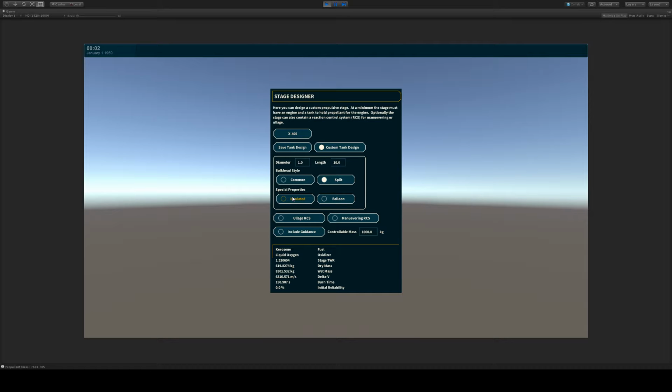You also have the ability to change this here, obviously. So we're going to go ahead and make this again something analogous to the Vanguard first stage, which is a 1.14 meter diameter. And you'll see as we do that and press enter, this is now updating. And so again, 12.2 meters high. Again, updating. Now, these values that you'll see here are not exactly the same as the Vanguard first stage.